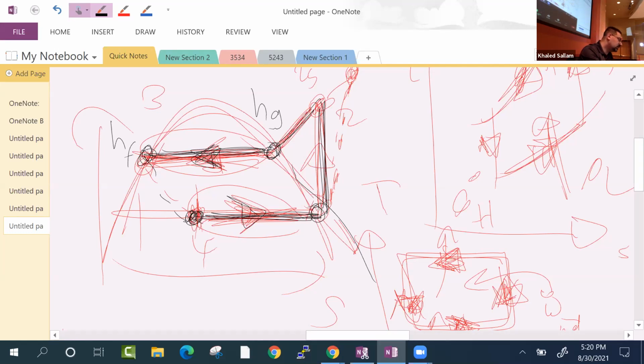What else is not good? And you remember when we calculated the COP? Steve said divide by work compressor, and I said, you mean work net? But then it's work compressor because the throttling device is not doing anything. So what don't you like then?